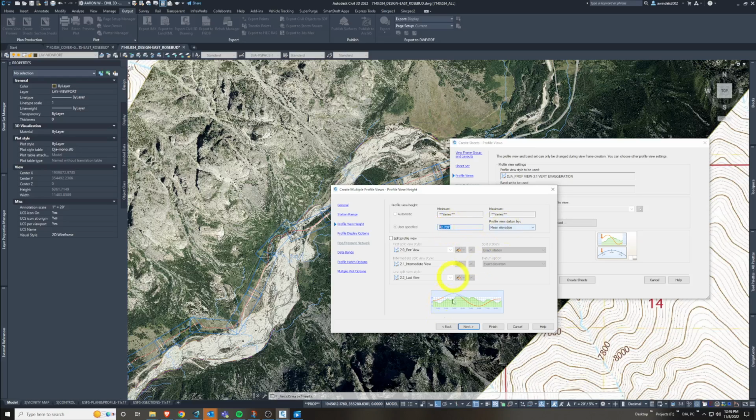It will try to make the height of the profile view and the elevation in the Y direction this amount. We'll have to go back later and change that to an even amount. It's kind of a pick one or the other thing, but they generally will keep it very centered very well using this, as we've found before. We're just getting better at maybe editing more settings here. It's not perfect, but it gets you on the right foot, and editing these minimally later is most of the goal here. You might look past this after you've got the mean elevation set.